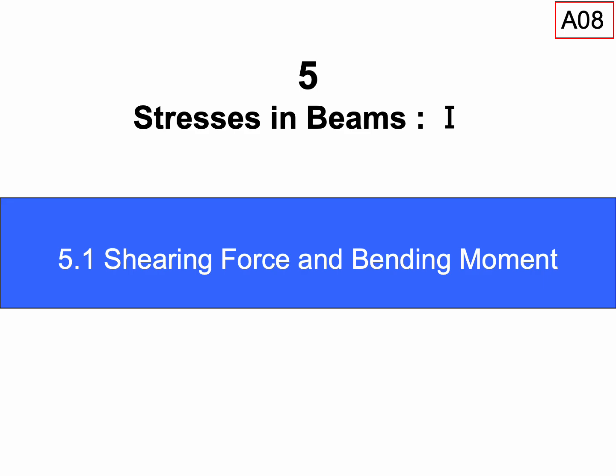The specifics of the supports are paramount because they determine the reactions generated by the structure against the external loads. We examine three main categories: the pin support, that is simple support, the roller support, and finally the fixed support. Understanding these support conditions is the essential first step, as accurately calculating the external reactions is a prerequisite for finding the internal forces.